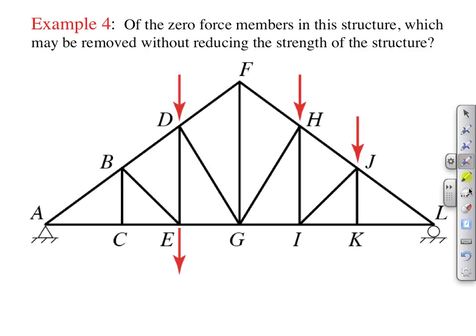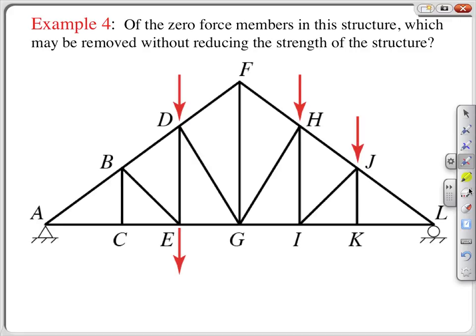Here we have a truss we examine in conjunction with the identification of zero-force members. Let's take a moment to identify those zero-force members as well as indicate the members experiencing the same load based on collinear equilibrium component equations at the accompanying joints. So we had previously found that BC and JK and BE were zero-force members.